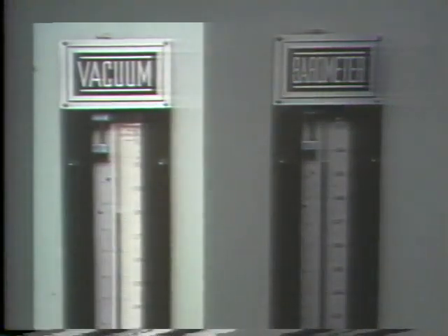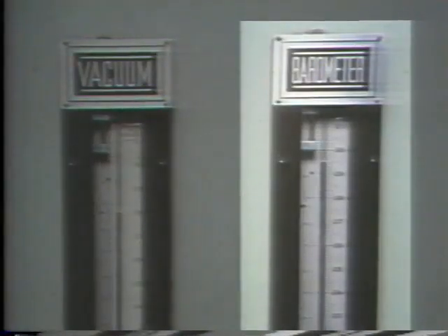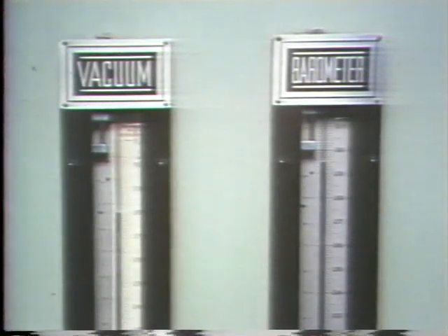But if the condenser has a vacuum, there will be a difference in pressure between both ends of the manometer. Atmospheric pressure will push the mercury towards the lower pressure end connected to the condenser. The greater the condenser vacuum, the higher up the mercury will be pushed. Operators use a vacuum manometer and a barometer to calculate condenser back pressure. Usually, the manometer for condenser vacuum is located right next to the barometer. All you have to do to find back pressure is to read the two. The difference between the condenser manometer reading and the barometer reading is the back pressure.